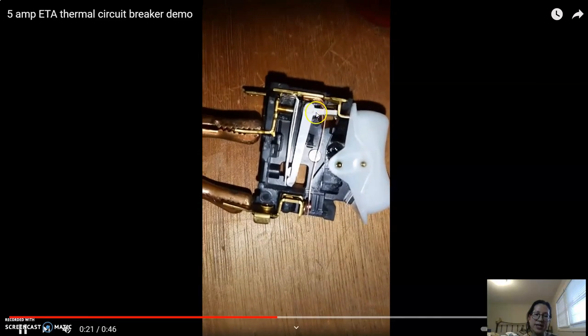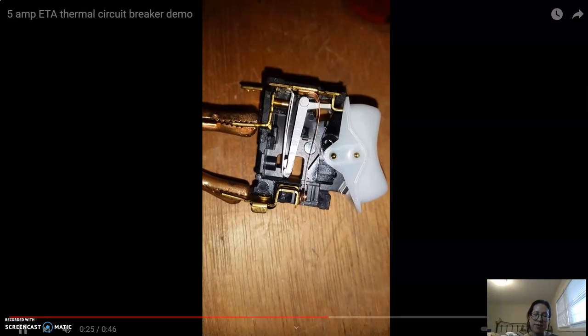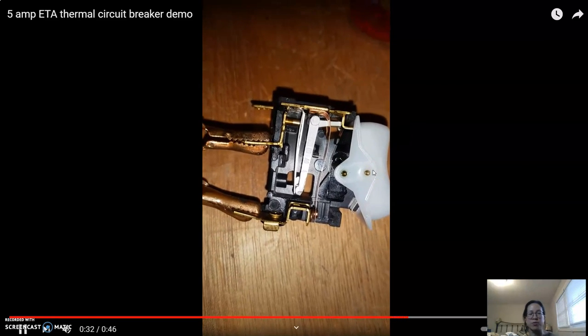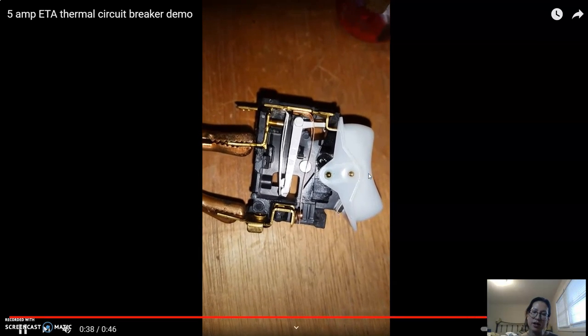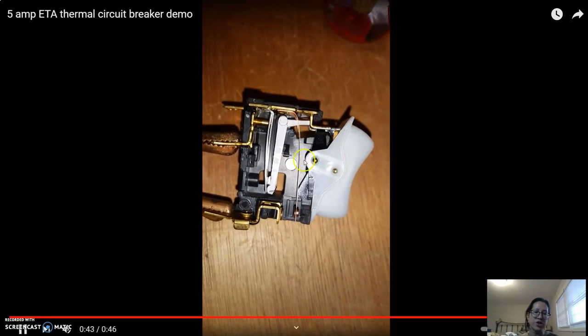And then what will happen is that this curvature will actually pop as one of them heats up, and then it will trigger the opening of the circuit. And then this would be where you press to turn your circuit breaker on and off. Okay, so let's just wait for it. There we go. So it just triggered it.